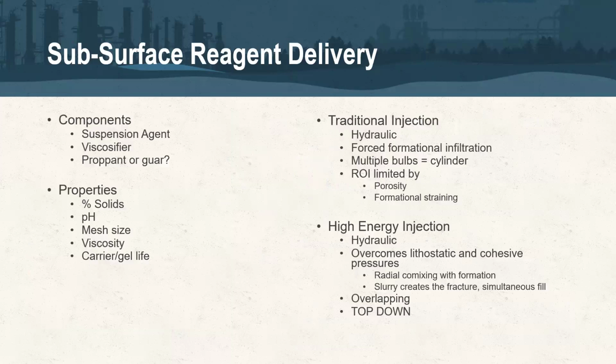Other ways to put slurries in the ground involve suspension agents, gasifiers, things that make a true particle suspendable, which this product, this ferroblack, is, right? This is a true slurry. So this isn't something that's going to lend itself to traditional injection equipment and injection techniques.